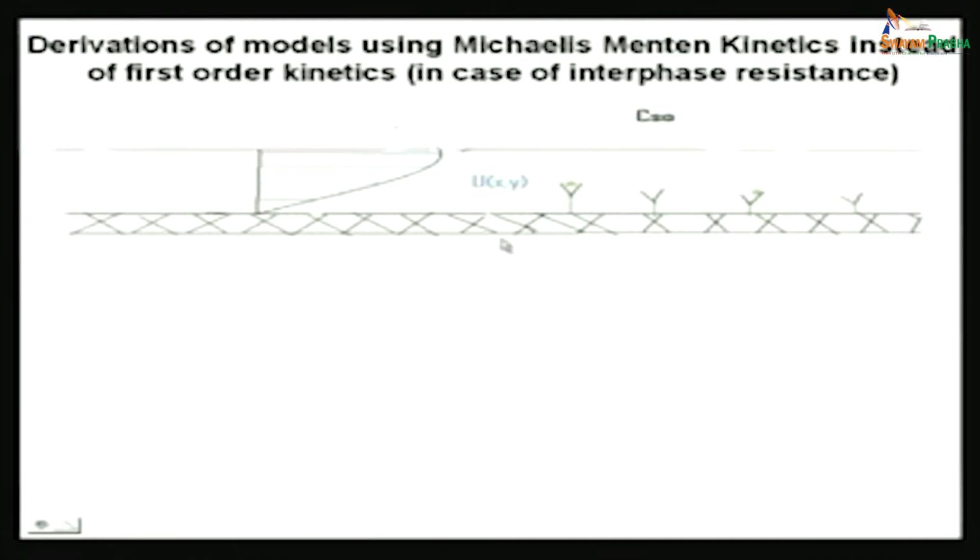So, the diffusion reaction equation or boundary layer convection diffusion reaction equation using boundary layer theory is not something you can solve analytically for a nonlinear reaction. It is not even something that you can solve analytically for a linear reaction, let alone a nonlinear one. So, obviously, that is ruled out if you want to get an analytical solution. So, the one that we are left with is the mass transfer coefficient, the use of mass transfer coefficient. So, let us do that.